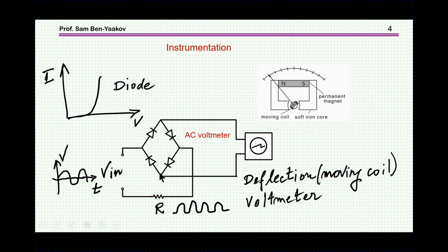Now, here we have an AC voltmeter. It's an old version, which has a diode rectifier and a moving coil instrument, or meter, or galvanometer, which requires DC for deflection. So we take the AC, rectify it. There is a limiting resistor that is adjusting the current fed to this galvanometer, to this DC meter, and the deflection will therefore be proportional to the AC.